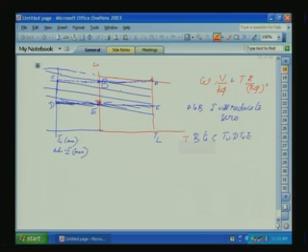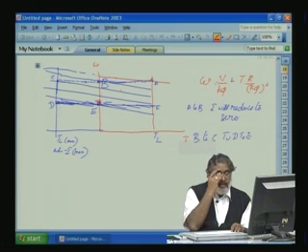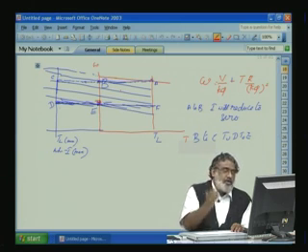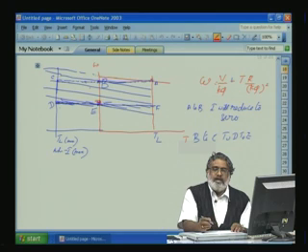So, speed cannot change instantaneously because the back EMF cannot change instantaneously because of the mechanical time constant. Mechanical time constant will always be greater than, we can assume here, the electrical time constant. So, A to B, the current will come to 0 immediately, and still we are controlling the voltage. With a slight reduction in the voltage at this point, the torque is 0, that means the back EMF will be equal to our applied voltage. So, current will be 0.